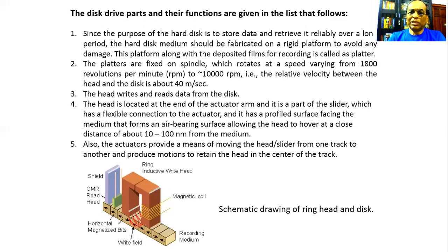It has a profile surface facing the medium that forms an air-bearing surface, allowing the head to hover at a close distance of about 10 to 100 nanometers from the medium.